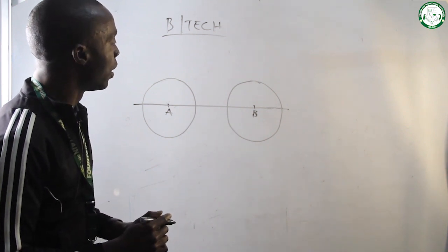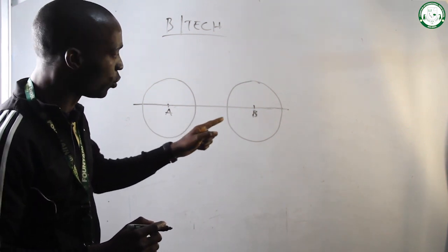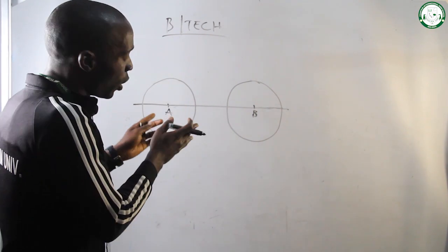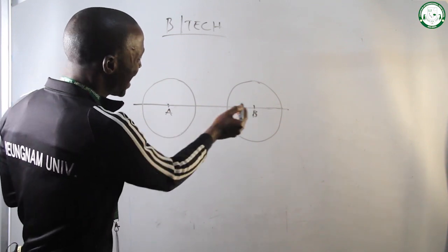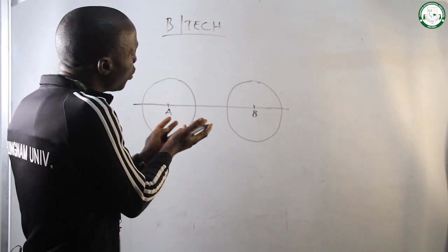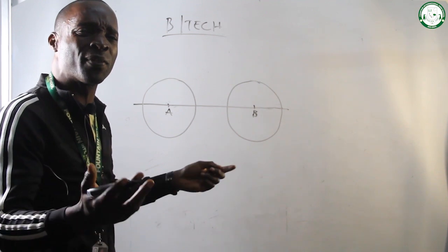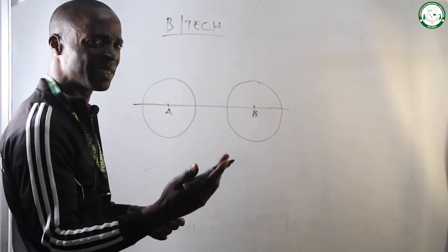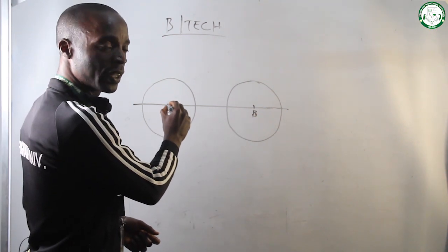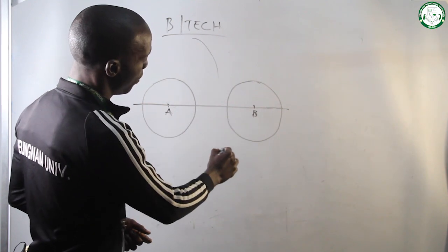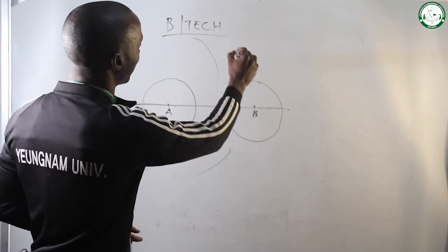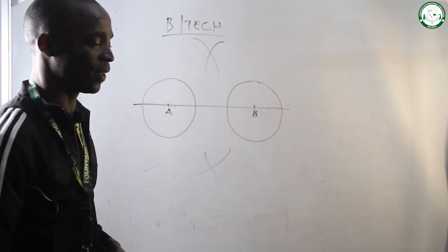Point C. Okay? To bisect AB, you must use a radius greater than the radius that you have just used. Just use a convenient radius, but use close to, let's say, 75% of this line. We center A and that convenient radius, cut an arc up, cut an arc down. With that same radius and center B, cut another arc up, cut another arc down to intersect the first one.